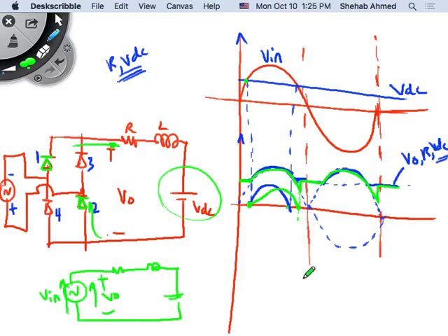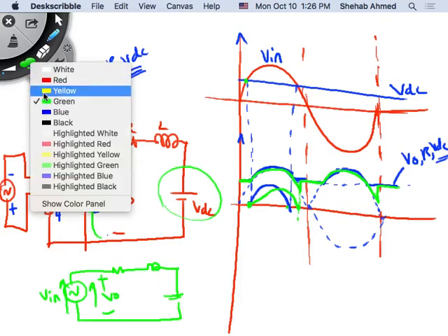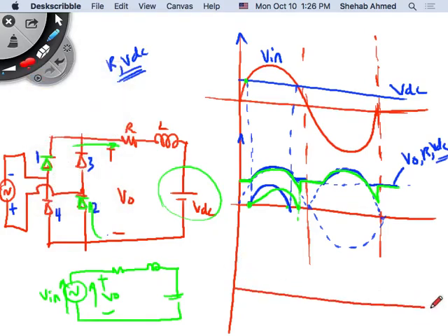So with different voltage, can we make it go beyond zero? Of course, beyond zero, this is a full bridge rectifier. If you try to go beyond zero, diodes 3 and 4 will conduct, like the previous case, and that's the other condition. This is called the discontinuous current case. In the text they also show the continuous current case, where instead of the current stopping here, the current starts rising and then never falls. This would be the continuous current case.